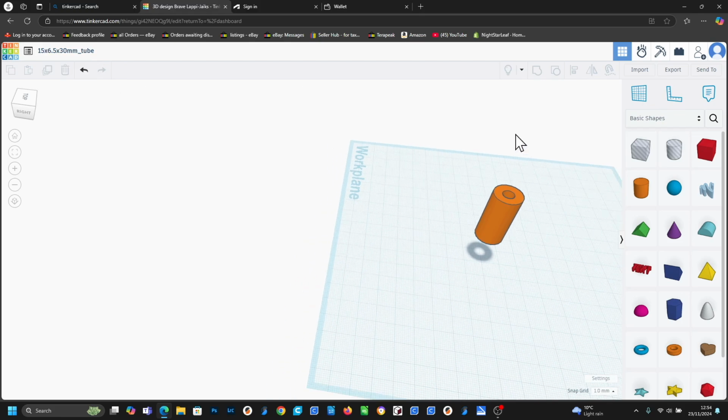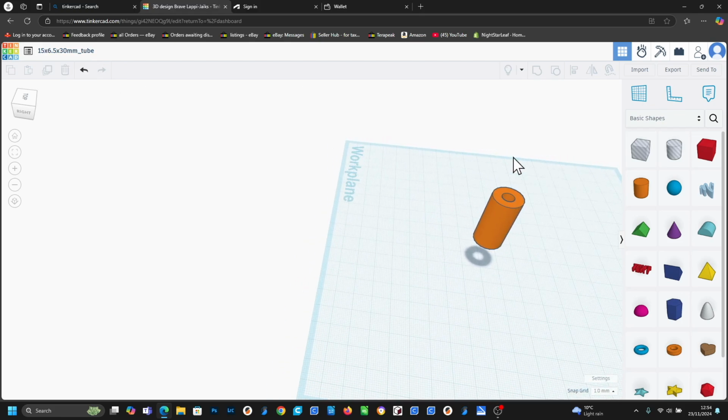I think I was mostly interested in how to manipulate things, and the align tool is a very good, very powerful tool to actually align things, instead of just having to guess or using the snaps. Here you can really ensure that the two shapes are aligned together, and make sure that the inner hole is in the middle of the outer shape, so it forms a tube. That's a really powerful thing, and I found it quite useful in this particular application as well.